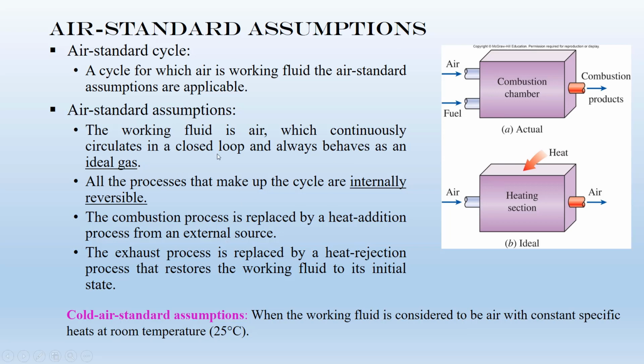In some cases, you may see this cold air standard assumption. If you see this statement, for example, use the cold air standard assumption, you need to assume that the air is at room temperature, and then use the CP or other thermophysical property of air at 25 degree centigrade, correct? So if you have this statement, for example, use the cold air standard assumption, just use the constant CP of air at 25 degree centigrade for the calculations. Okay.